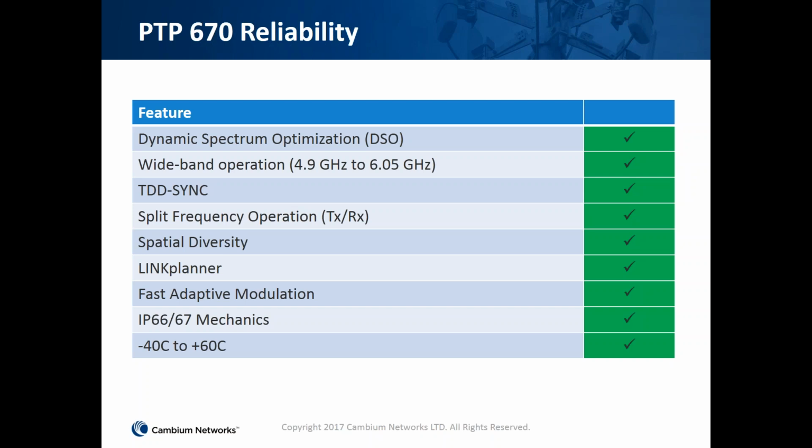Basically what this means is you can use different frequencies for uplink and downlink. So if you think about it, when would this be useful? Let's say you are already deployed in a network, and you want to deploy it in 2 points, but there's no common channel bandwidth that is free on both ends. Let's say you have 5.1 free at tower A and 5.8 free at tower B. So there's no common channel that you can use to get the maximum throughput.